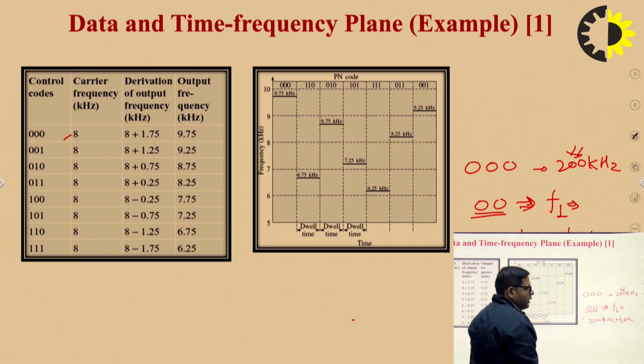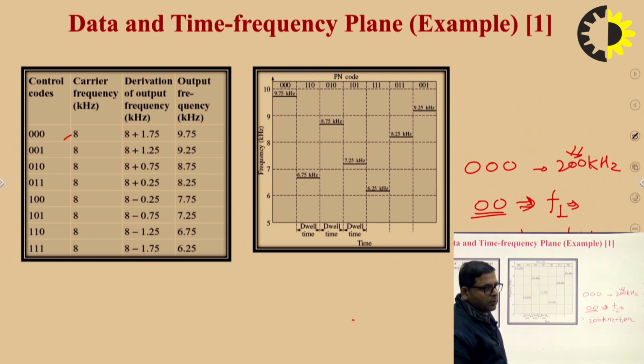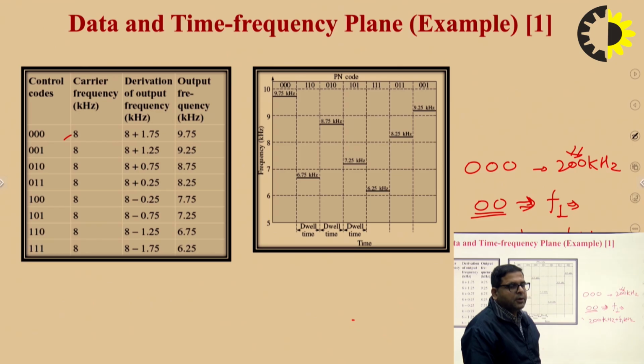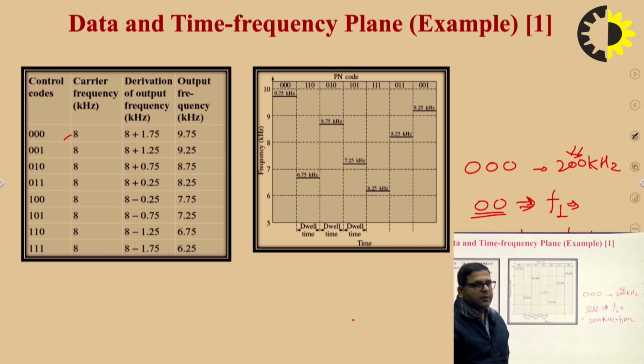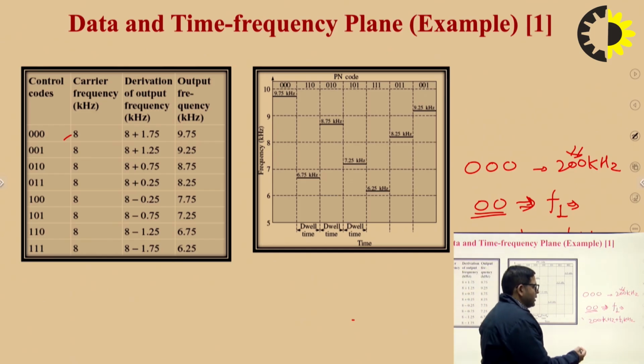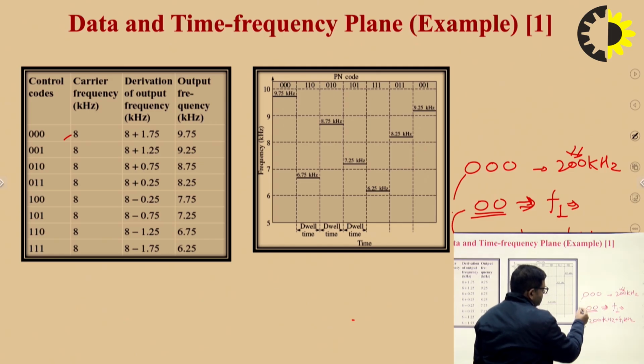Now, there are two kinds of frequency hop spread spectrum, slow and fast frequency hopping. In slow frequency hopping, we can transmit multiple symbols during one frequency hop. So I am taking the example of slow frequency hopping. The frequency synthesizer frequency is the same, but we have another bit to transmit, for example 0 1.